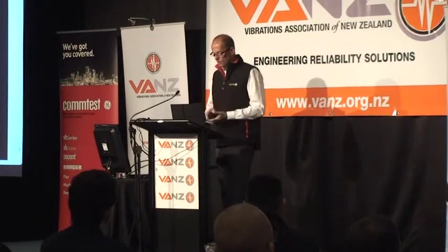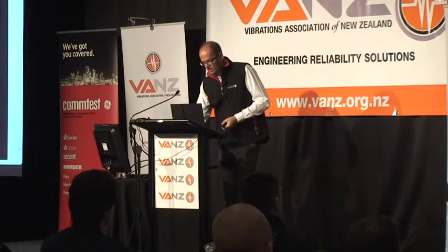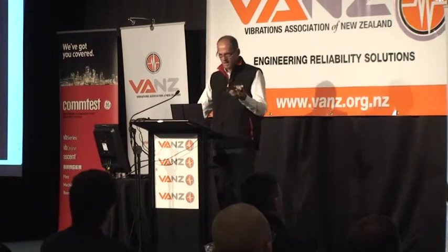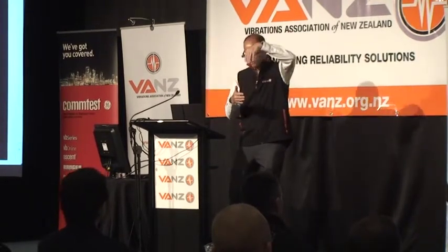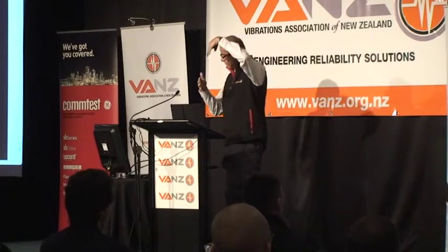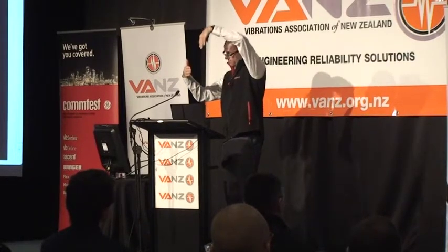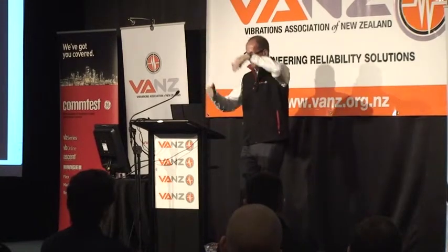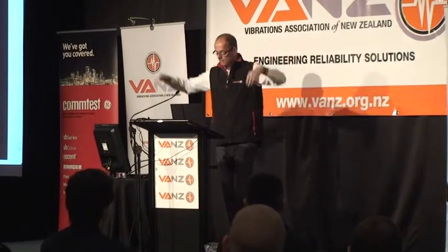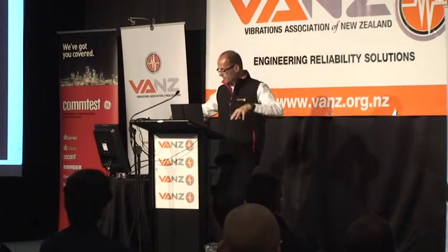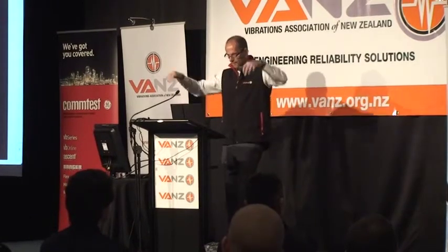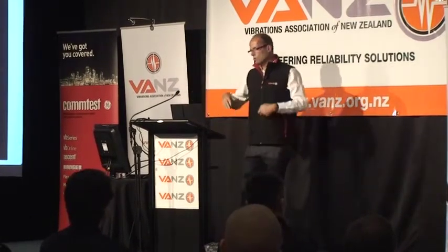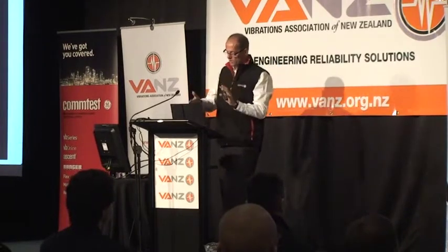So now you can sort of visualize, well, this is moving in a circular motion. What does that tell me from a phase point of view? Between vertical and horizontal, that would be 90 degrees. I've got my sensors 90 degrees apart, so the phase should be 90 degrees apart. If I put sensors at either end, that's all moving up and down together, so they would be in phase either end. And there's all sorts of things we can do depending on the type of machine.